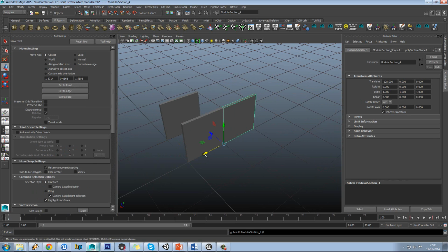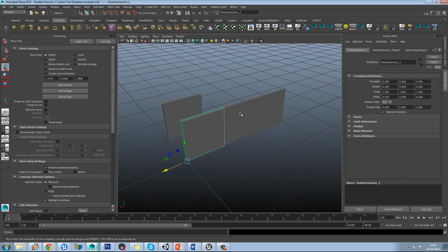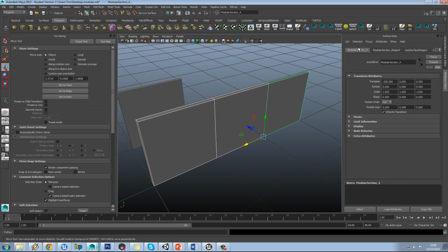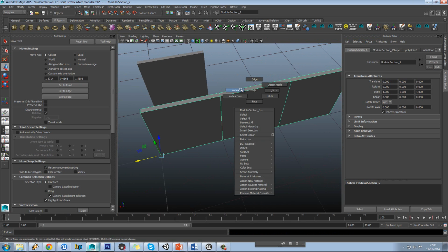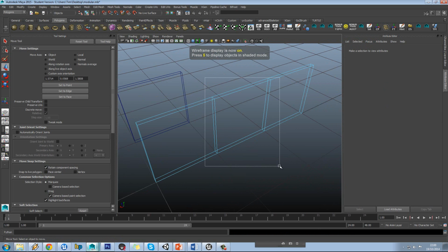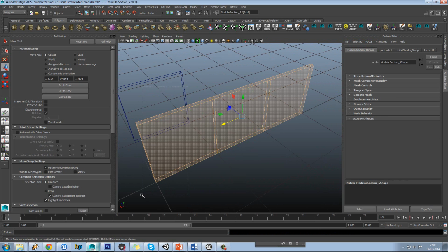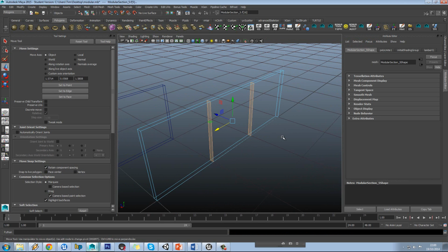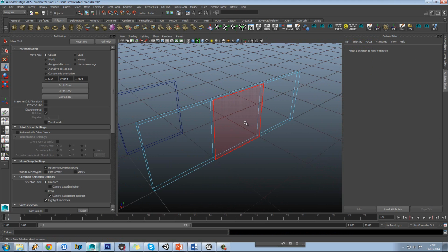What we're going to do is just copy this 3 times because we know our wall is 3 pieces long. So we'll select these, go to Combine, and what we'll need to do is get these 2 inside faces. So I'm just going to select these and then hold Control and just minus off those off the selection and delete those out.